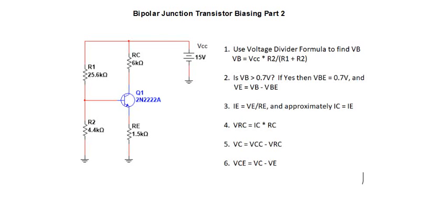Here on the left is the circuit. We looked at this circuit last time without the voltage divider attached, just the collector and emitter parts of the circuit. And we determined something that we call a load line. We found the two endpoints, which is a saturation current when VCE is 0, and the cutoff voltage.